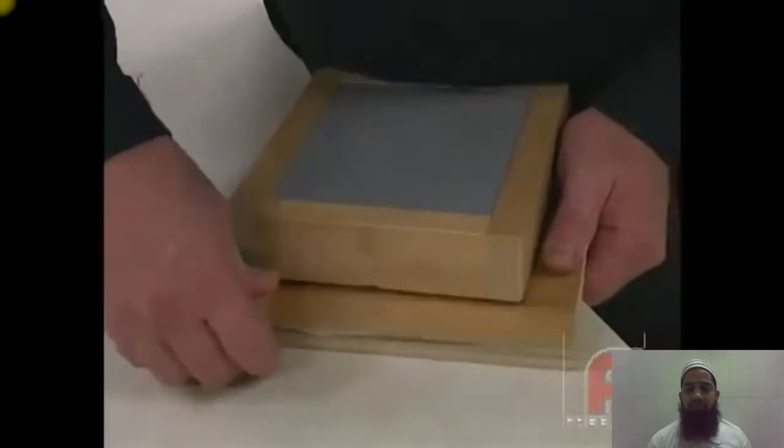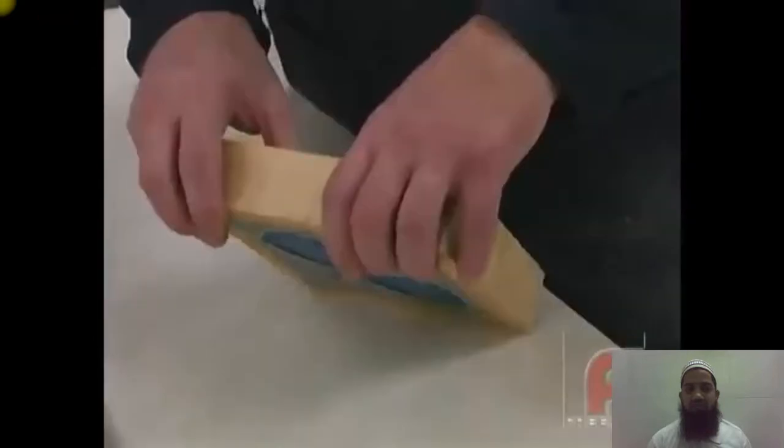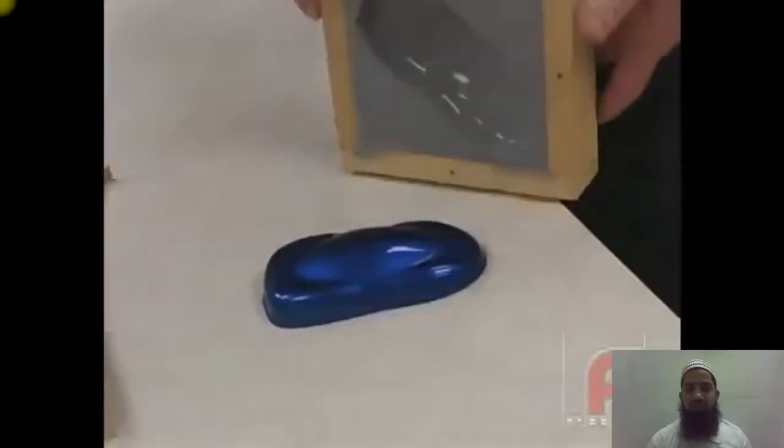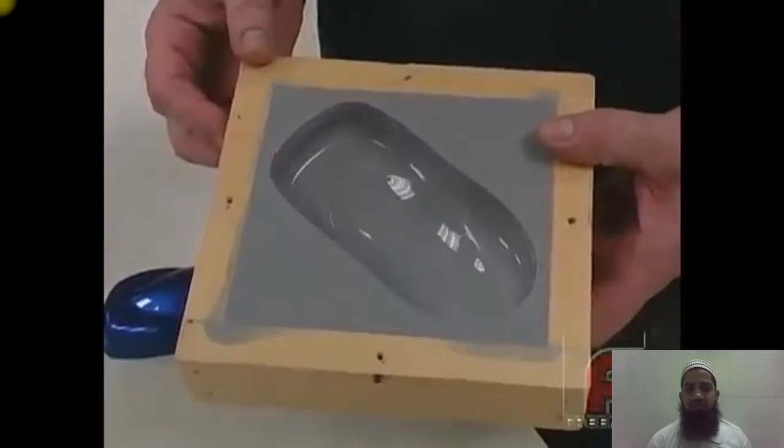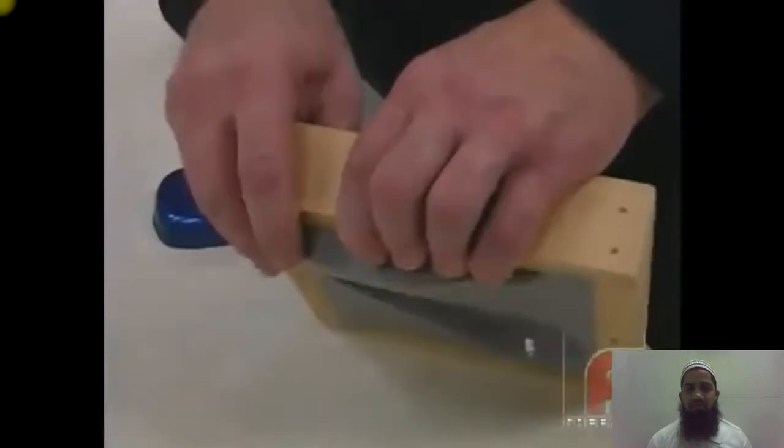The next day, our mold is ready. We remove the screws and then wedge the whole thing off with very little effort. Next, we pushed out our model from behind. Notice how accurately the silicone reproduces the surface of our model. Next, we pushed out the mold itself and pulled off the edges with our fingers.